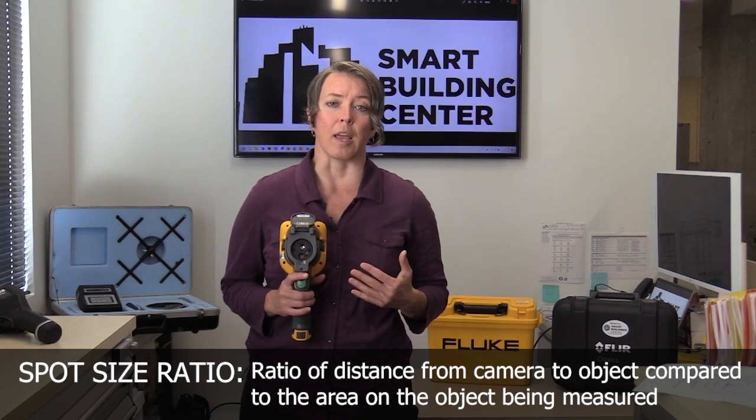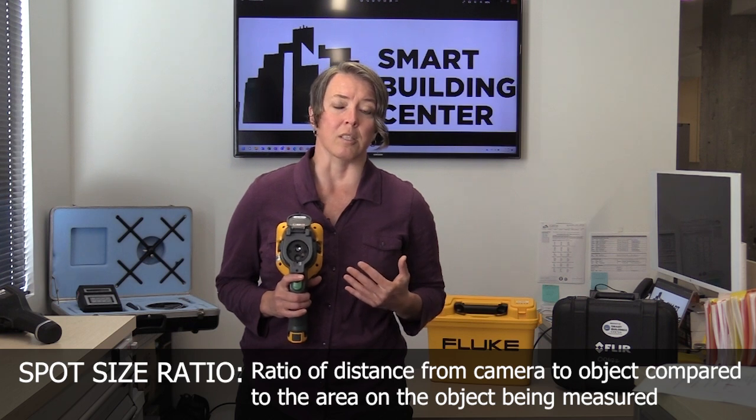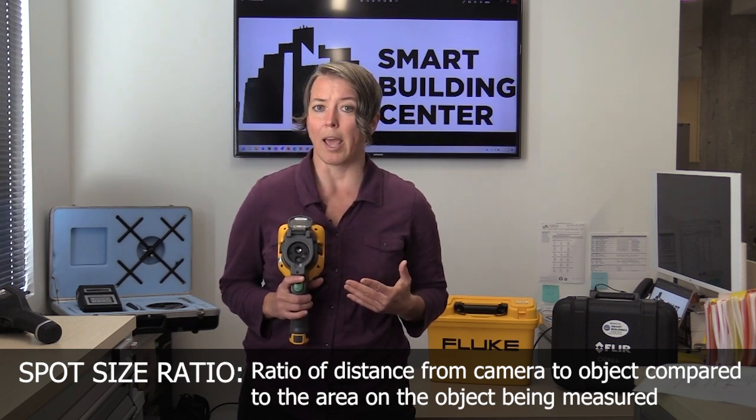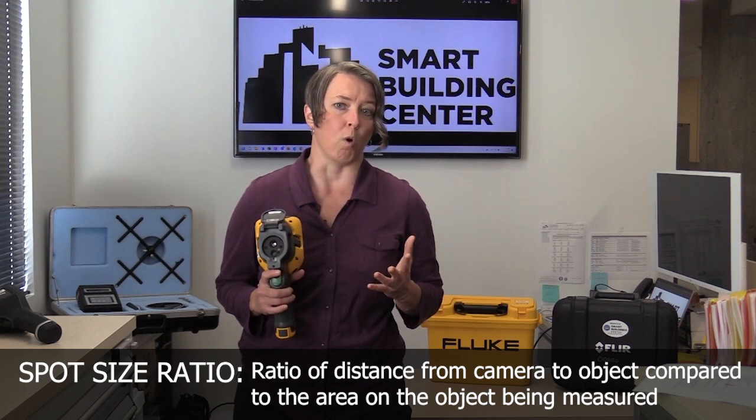For example, a spot size ratio of 24:1 means that at 24 feet away, you can measure an object up to a foot wide. The ratio can refer to any measurement, it could be feet, meters, etc., as long as both components are the same, so the distance to the area being measured.